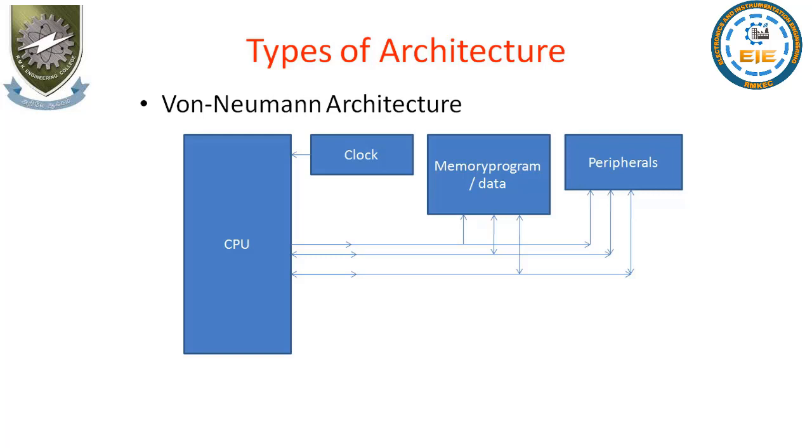The von Neumann architecture consists of three buses: data bus, address bus and control bus. The data bus is used to transport data between the CPU and its peripherals. It is bidirectional. The CPU can read or write data in the peripherals. The CPU uses the address bus to indicate which peripheral it wants to access and within the peripheral, which specific registers. The control bus carries signals that are used to manage and synchronize the exchange between the CPU and its peripherals, as well as indicate whether the CPU wants to read or write the peripherals.